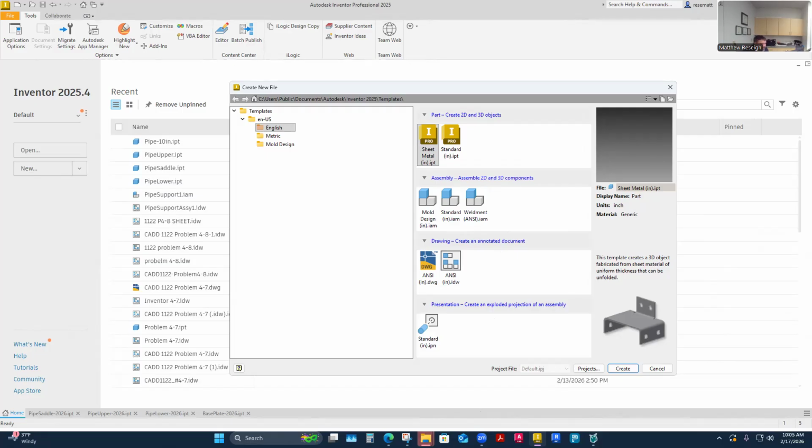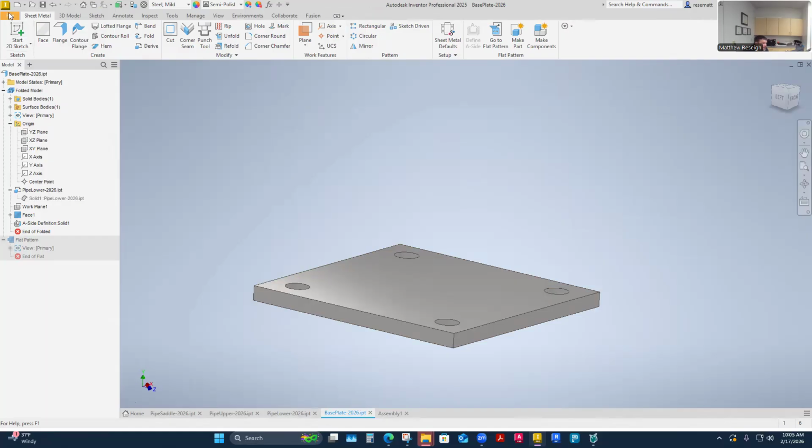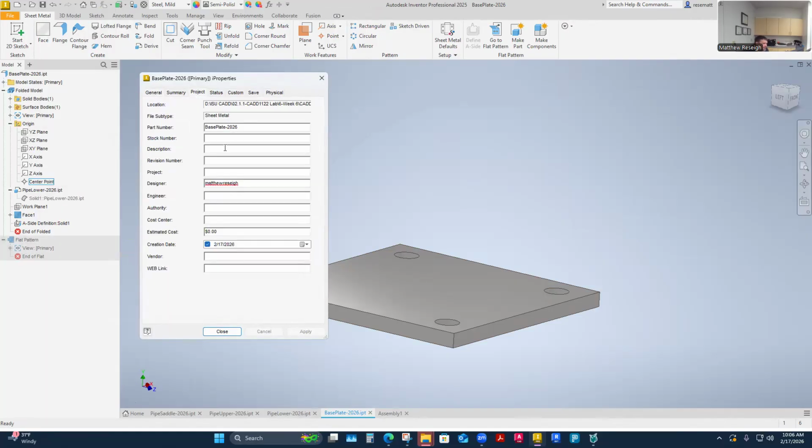Oh, I didn't update the iProperties. Good call. Let me do that. I'll just go ahead and start my standard assembly. I'll create it just so I have it open here. There's my assembly, but yes, let me update this. iProperties on this plate should say half inch mild steel plate. I probably have this wrong. Is it MS plate or maybe I said plate MS, but I'll fix those when I see my parts list description. Half inch mild steel plate. Yes. Okay.